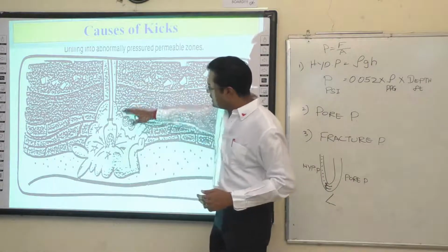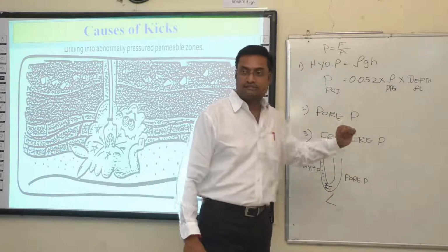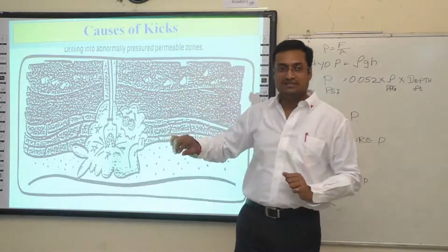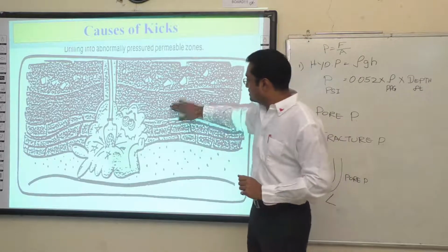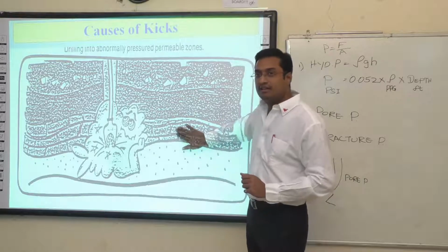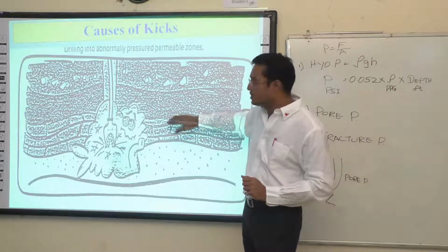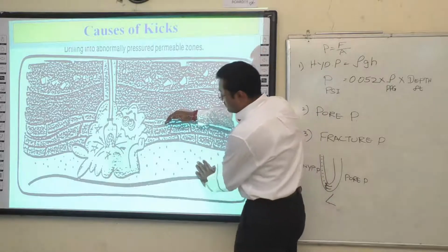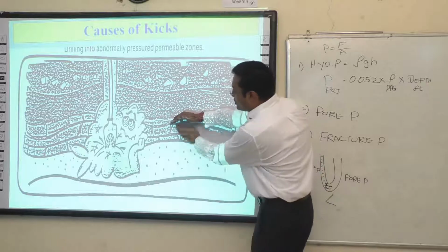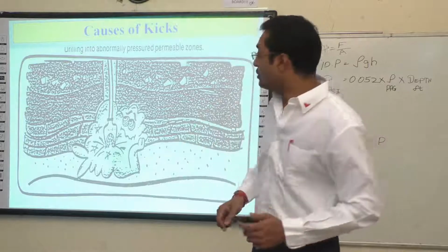when there is a change in formation, each formation will have a different pore pressure because of the characteristics of the rock matrix. If the rocks present here are not permeable, the fluids getting collected here get trapped and the pressure starts increasing here. Because it is trapped here, the formation which is giving out hydrocarbons will start acting at this place because it is getting accumulated.